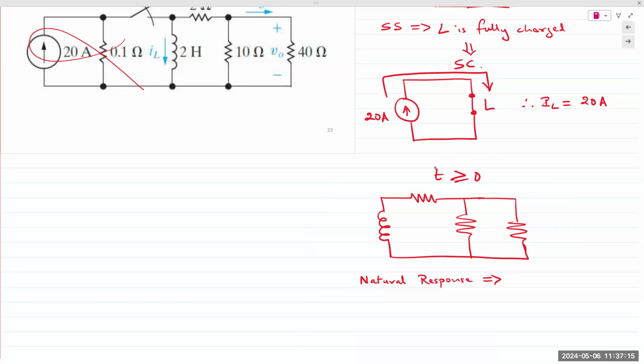It's releasing all of its energy, meaning at some point, the inductor current has to go to 0. So the final value, the end point of your analysis, IF, the value of the inductor current, will always be 0. If it's a capacitor, the final value for a discharging capacitor will always be 0.